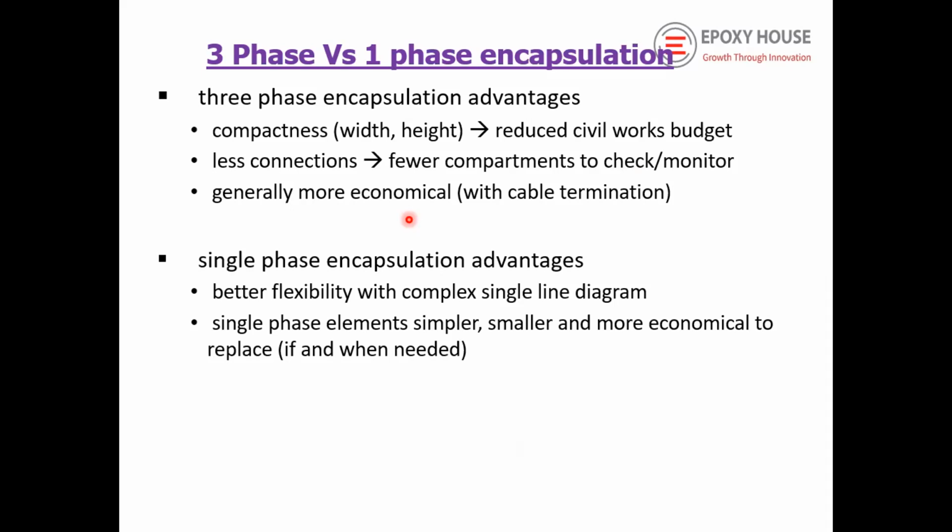There are also disadvantages, but some advantages: three-phase encapsulation has advantages because of compactness. The three phases are enclosed in one enclosure, so the weight and height are reduced. It has fewer connections, because otherwise you would need three separate boxes for individual phases. The number of enclosures is reduced to almost one third.